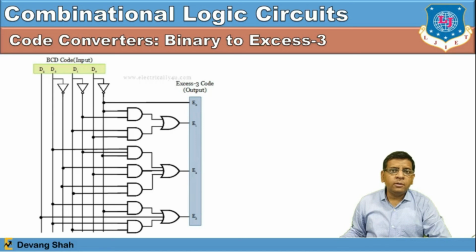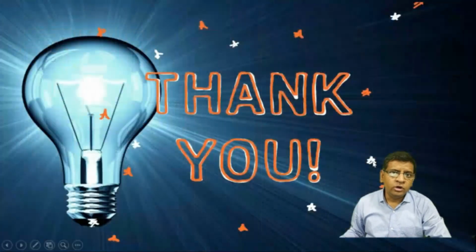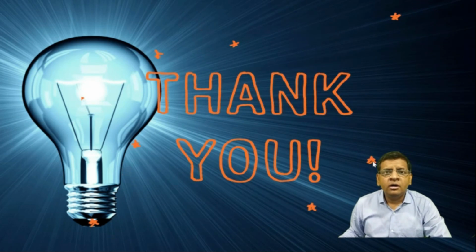So in this particular block you have a combination of AND, OR and NOT gates, and it looks like this. So this is what the binary to excess 3 conversion is about. This is a part of combinational circuits, and this is also a kind of code converter, right? So from this particular session you learned about the design of digital circuits for code conversions. Thank you very much.